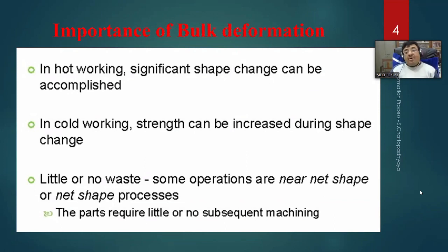So that is called strain hardening. Clear? That is sometimes an asset, sometimes a liability. Where it is an asset, I want a surface which should be hard, where there will be a lot of wear and abrasion. If the surface is hard, it is very difficult to take out the material.